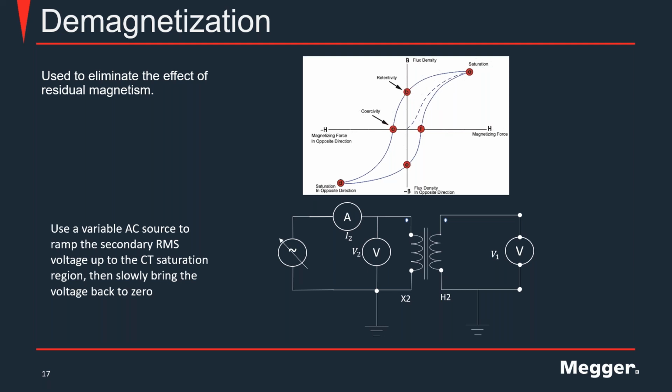Okay. So Daniel, when testing CTs on a power transformer, does the residual flux captured in the power transformer's core cause errors? And if yes, how do you correct those errors? Does one need to demag the power transformer core? Okay, so on the first section, when you are testing ratio on a CT on a bushing on a transformer, yes, you do need to worry about the effect of the windings of the transformer affecting your results.